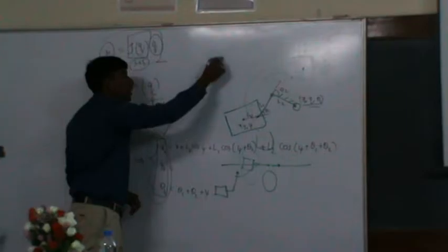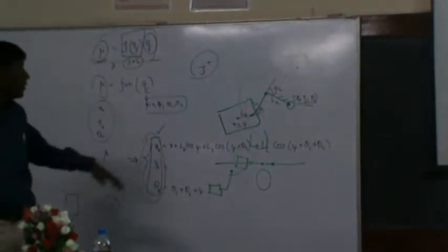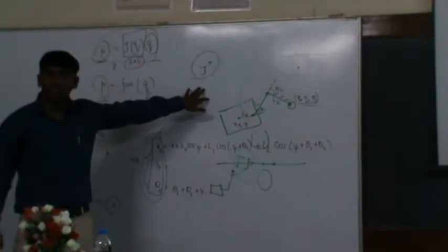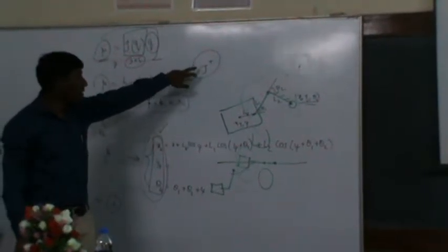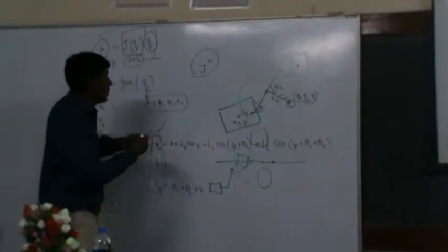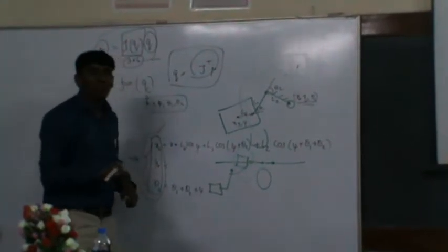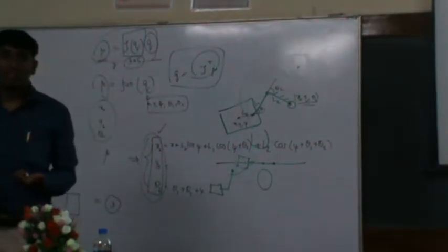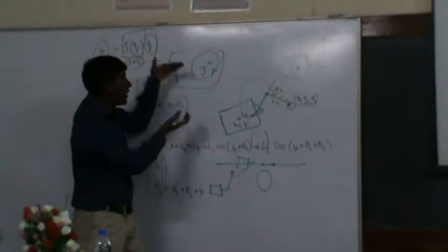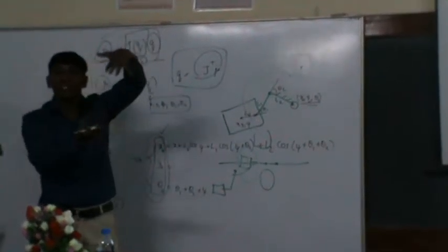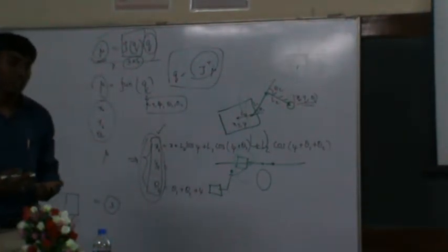If you recall the pseudo inverse, the Penrose or pseudo inverse, the background says it is least squares based. Indirectly, this will give the minimum norm. So if I apply just J plus into q dot, this is the least possible velocity of joint space. This way itself I can minimize the total energy required, because I already got the minimum norm of velocity.